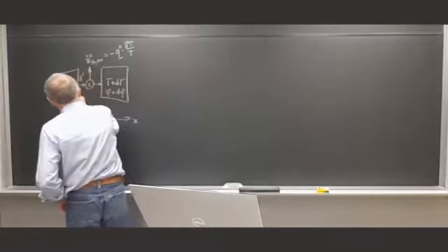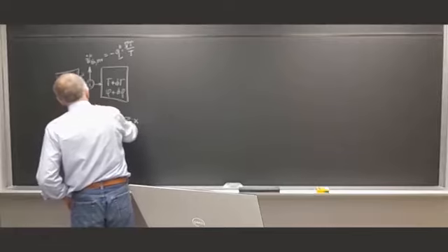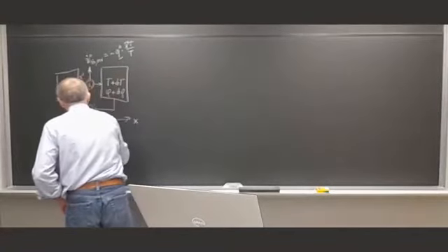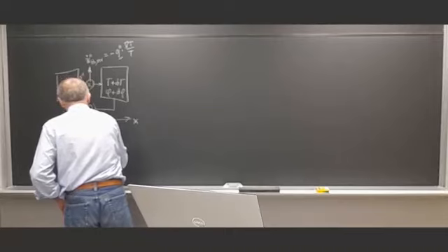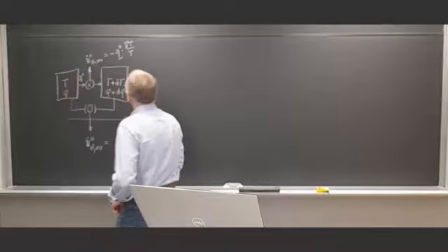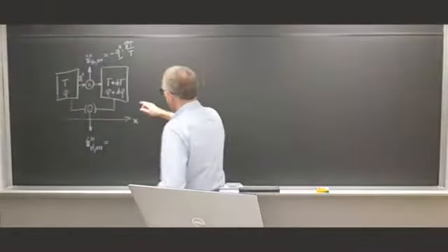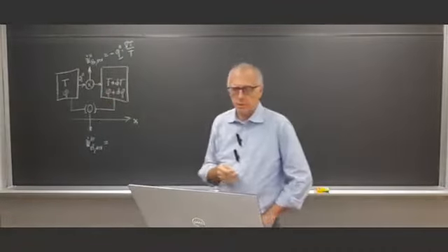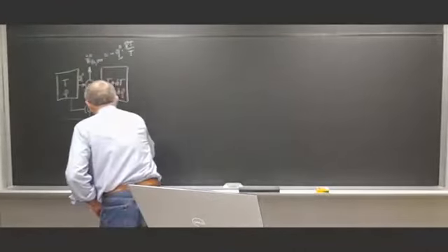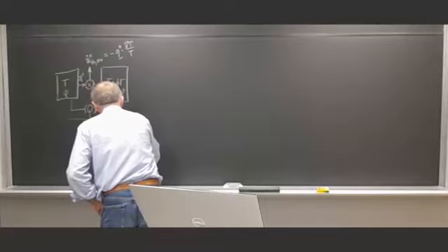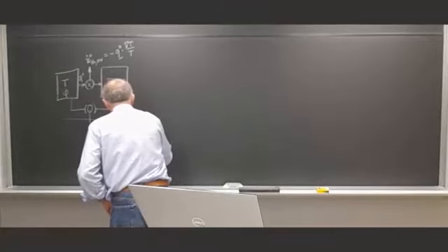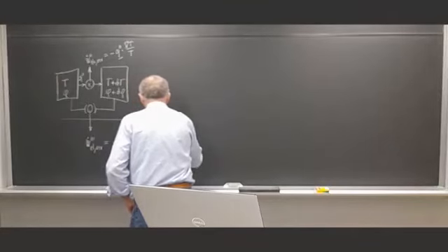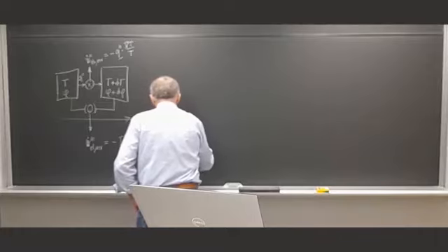So we can use that by extracting with an electric motor, for example, some work also this way, and that will add an electrical work reversible, which is given by, since the gradient in the electrostatic potential is driven by the Seebeck effect, minus I times the gradient in phi, and that's minus I times epsilon gradient in T.